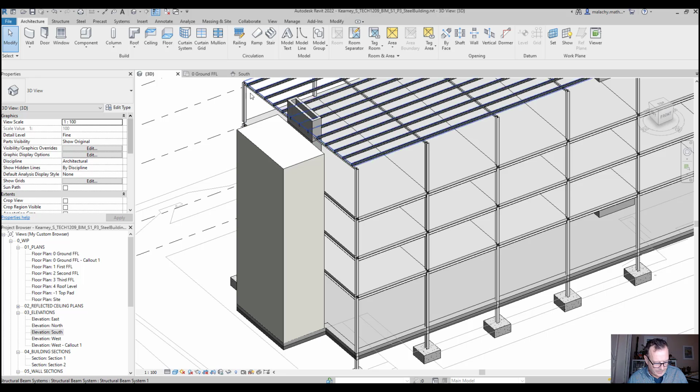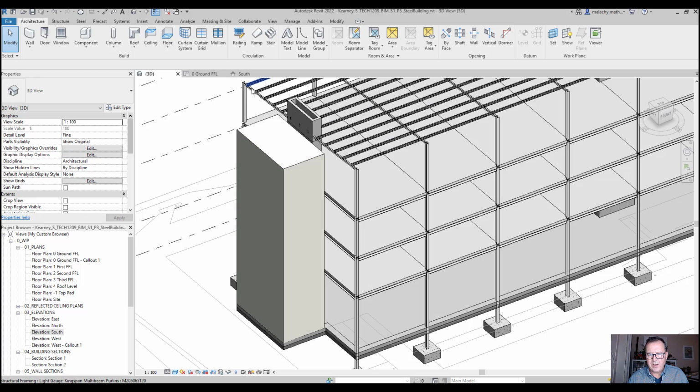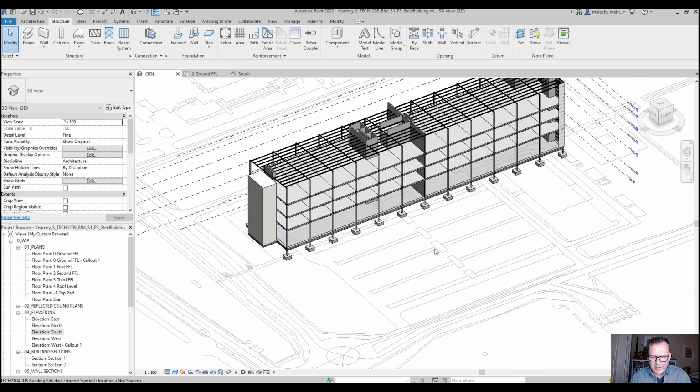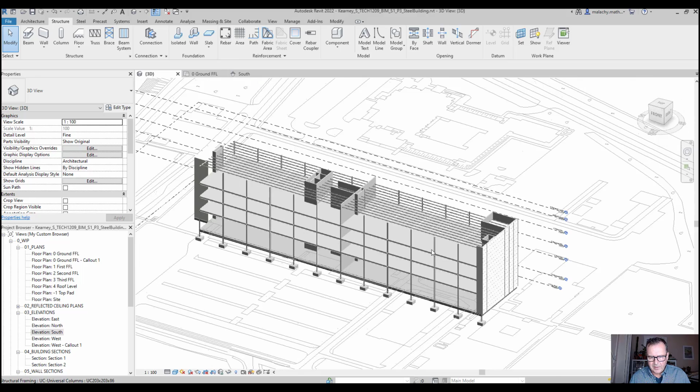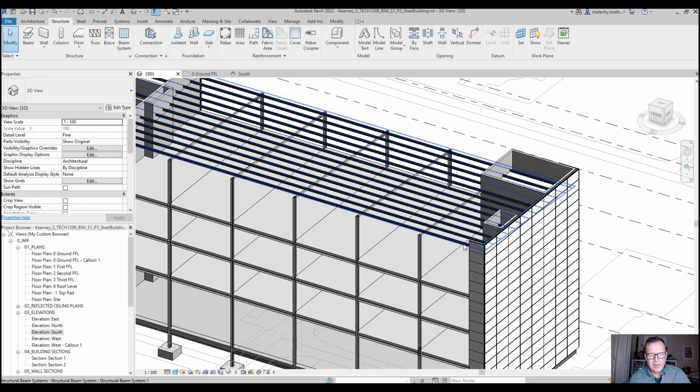All right, so there's my plan. Now, once you've got that technique sorted, then you can come over here to the other side, and you're going to do the exact same. You're going to bring the curtain wall all the way around like so, and around the corner here and around the corner there. First of all, you will apply the technique of putting in the horizontal beam systems, and then you'll draw in your curtain wall and substitute out the panels into that.